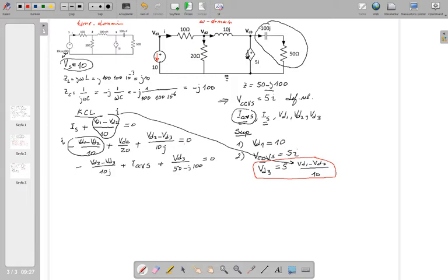So now the number of equations is 5 and the number of unknowns that we are trying to calculate is 5, so there is a unique solution, no problem there. You might say that 5 equations, 5 unknowns is not easy to calculate, but don't worry that much, because if you examine these equations now, first of all, VD1 is equal to 10, that means you reduce the number of unknowns, isn't it? So this is the solution.